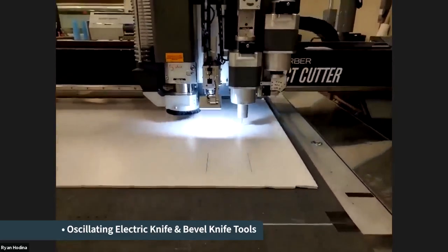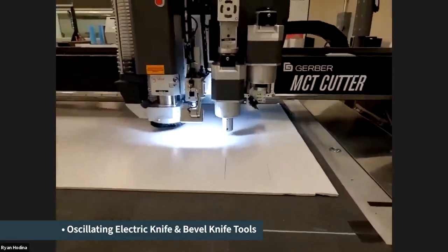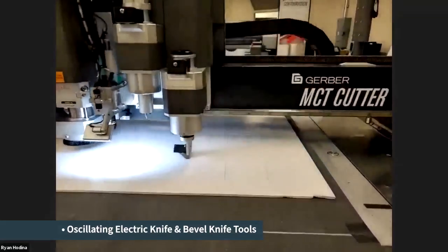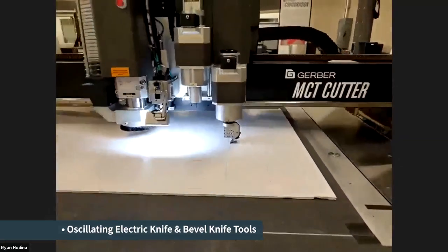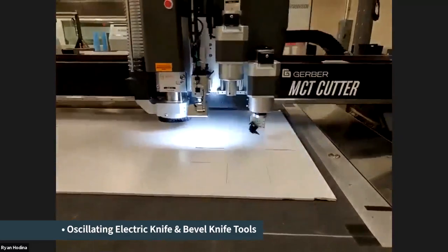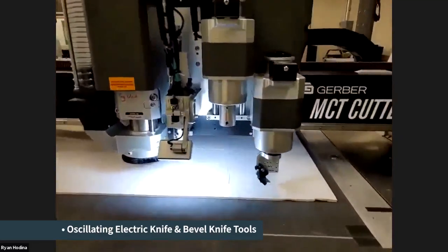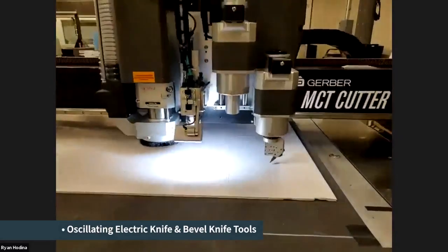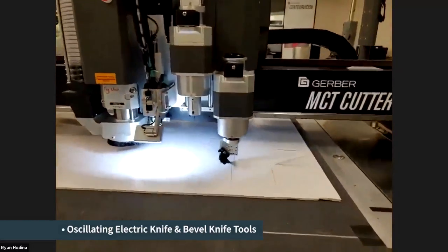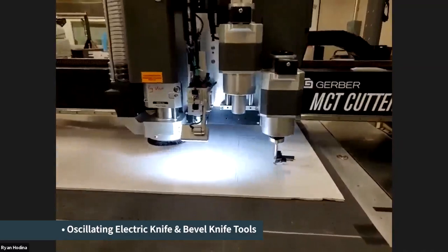So that's the electric oscillating knife tool that's running right now, and that'll be used for most of your thicker materials. And now we're using the bevel cut tool. We're using that to cut a channel in the material so you could fold that. It cuts a channel in one direction, then it cuts a channel in the other direction, like a V.